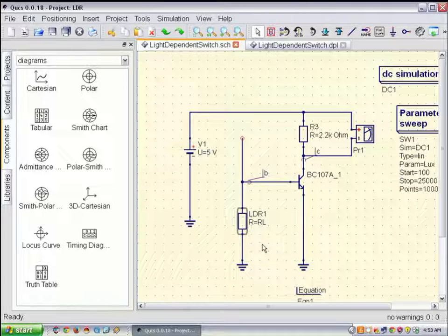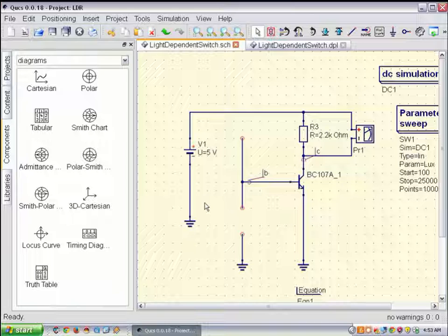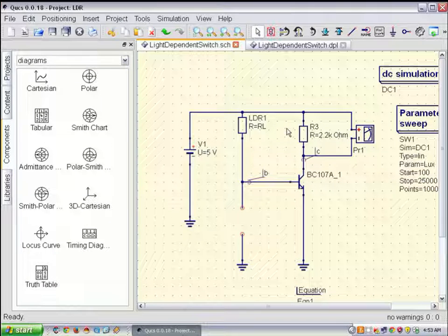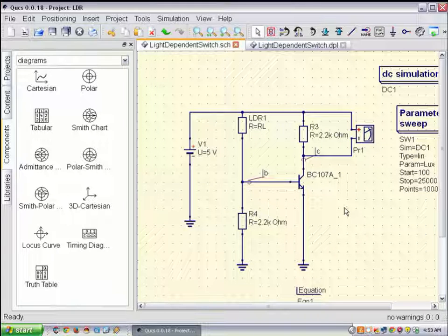Copy and then Control V. So I brought back this LDR there. Now I'll select R3, Control C and then Control V. So I just change the position of these sensors, the light dependent resistor and its current limiting resistor. Now we run F2 again.